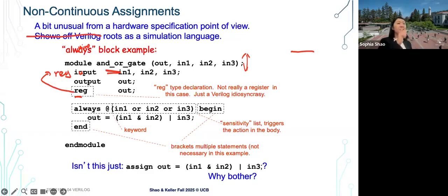So always block can be, we'll talk about, I think you're thinking about latch synthesis. There is a scenario when things are done incorrectly where the hardware will actually generate a latch. But in the majority of cases, whenever there's a latch, it's never intended. That means something is wrong in your hardware. And in this particular case, it will not generate a latch here. We'll have an example. But whenever you see a latch being synthesized out of an always block, we'll talk about flip-flops and latches, it typically means something is wrong in your hardware. It's not intended.